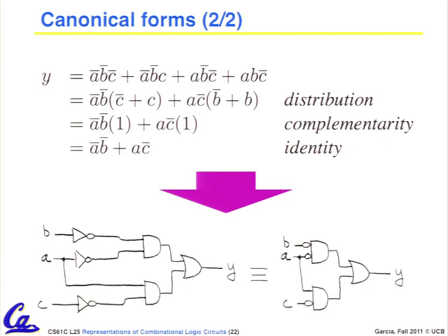They are the same. Equivalent means the same. Oh, well, talk about efficiency. Do you know the answer? They're not the same. This guy, I need a 4-input OR gate. The top guy needs 4 3-input AND gates.